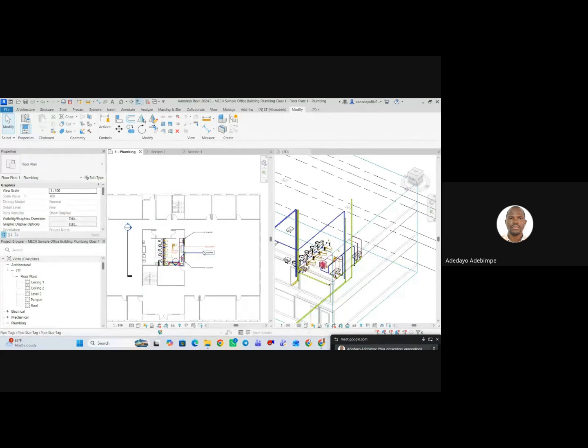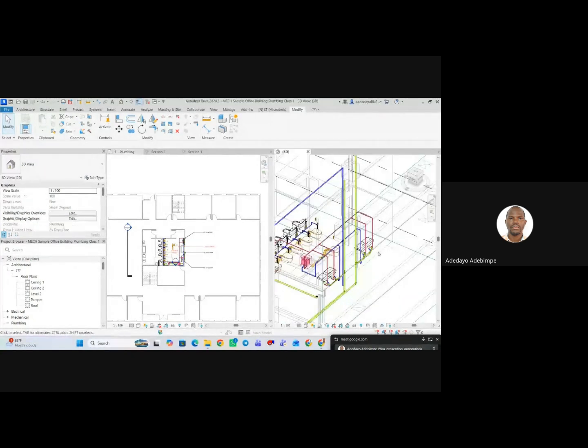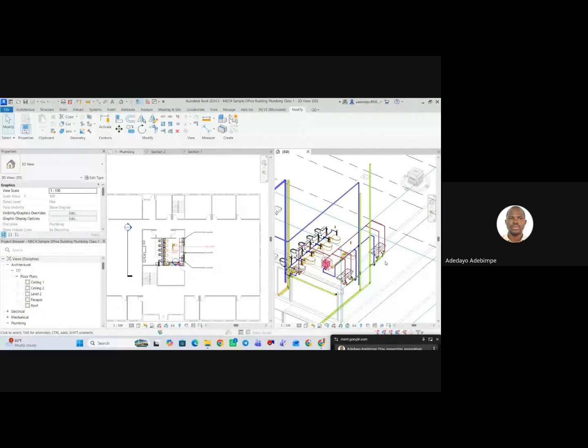They've designed rightly, and because we've designed, look at what we've done here. We've tried to simulate what is going to happen in real life as much as possible. So wherever I'm going to have elbows, my quantity of elbows here should not exceed, give or take, what they should use on site, in addition to maybe a 20% margin for wastage and all. So I'm not picking numbers out of the air. Now let's generate our schedule for the pipes that we generated.